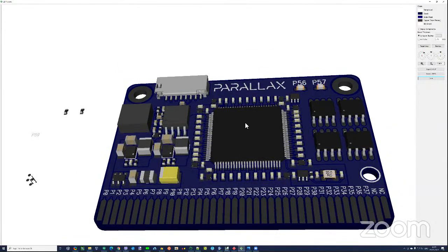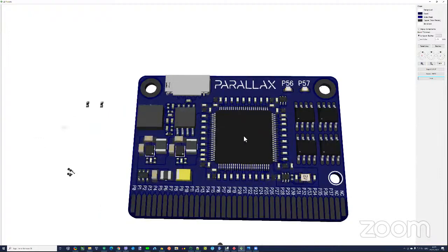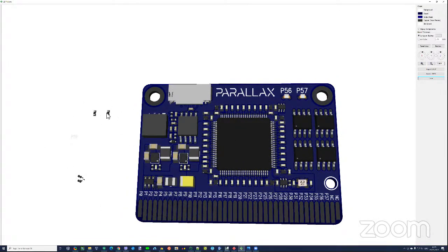zero, one would hope. But yeah, so the last thing that we are just changing is that there's two resistors over on the left-hand side here. I need to find a space for them. They're going to be pull-ups on the TXRX lines. The existing Edge didn't have pull-ups, but we thought it's a good opportunity to include them.